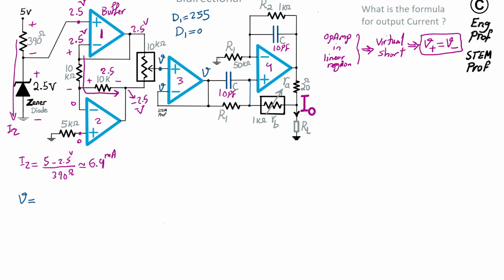We can program it ourselves. So I can say this voltage V is equal to the lowest value, negative 2.5, plus the delta 5 times number of steps, so steps being the code word divided by the 256. So basically what happens, we get 2.5 volt times D1 over 128 minus 1.